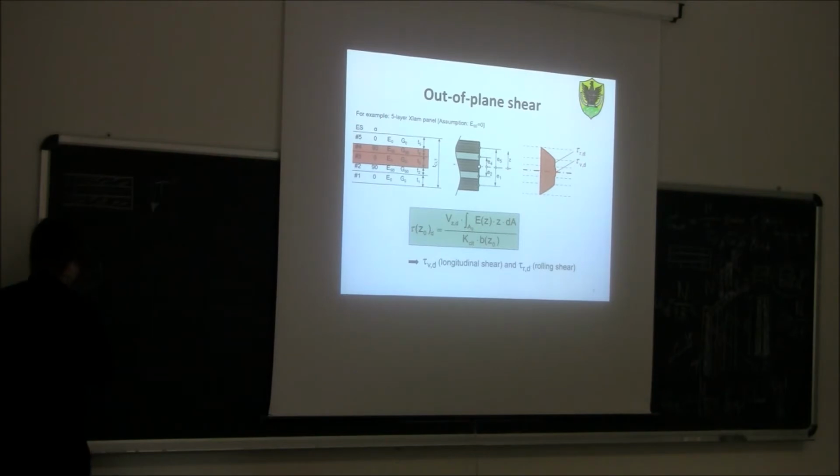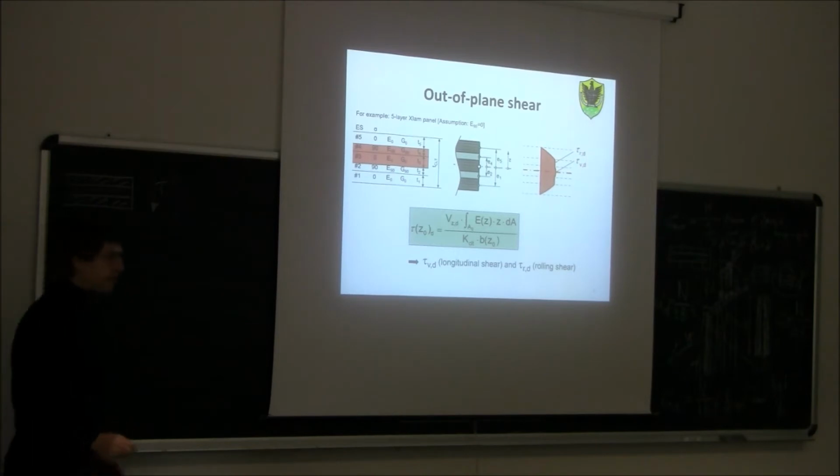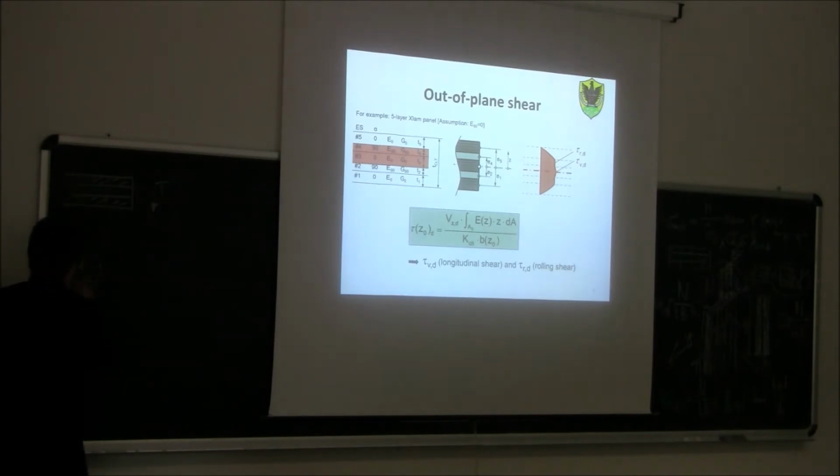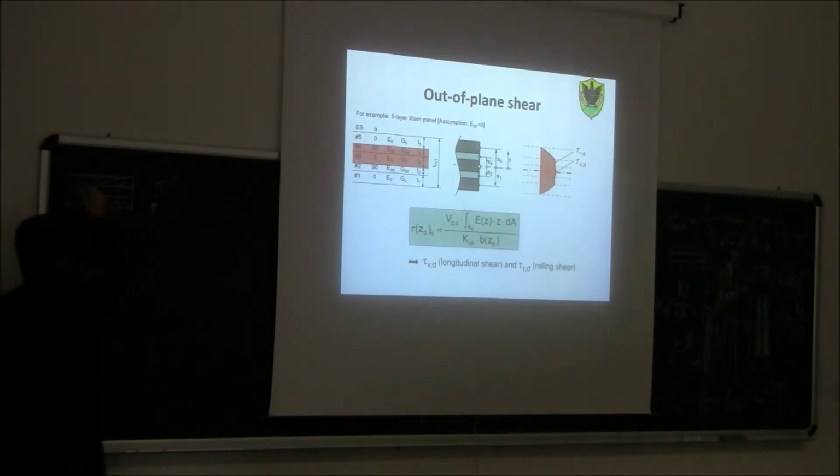So if this is the shear, the bending moment should be in this plane here, right? And this bending moment, in this direction or in the other, is going to induce some stresses in which layer? The stress will be in this direction, so the resisting layers will be these two here, exactly like before. So those are the effective resisting layers. Okay?